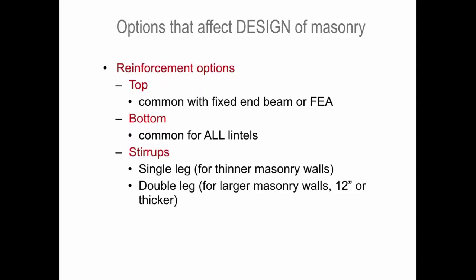Engineers know that, right? It's going to crack, because you have that negative moment there. You don't have the reinforcement to resist the moment, so you have some little cracks that are created. If you want a really robust design, you add the same amount of reinforcement, but just split it between top and bottom, right? And top reinforcement should be becoming more and more common in masonry design, masonry lintel design.